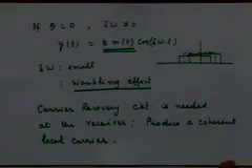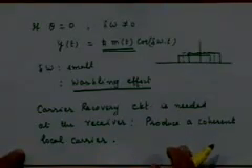So there are special circuits one has to make to carry out this carrier recovery operation, to make sure that your local carrier is in phase and frequency synchronism with the incoming carrier. And that's why a synchronous demodulator is typically a complex operation, because you need to worry about this, right? You need to worry about carrier synchronization. Okay.